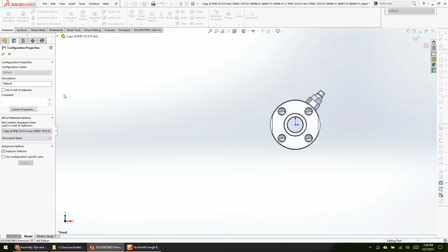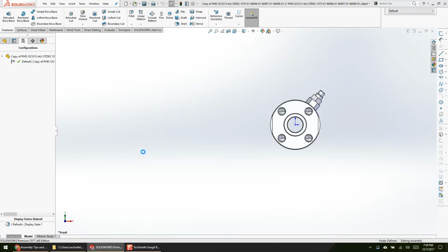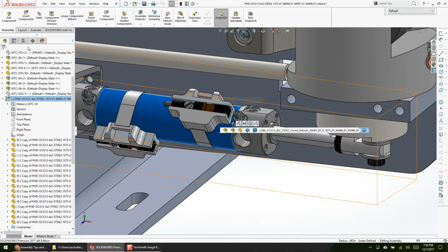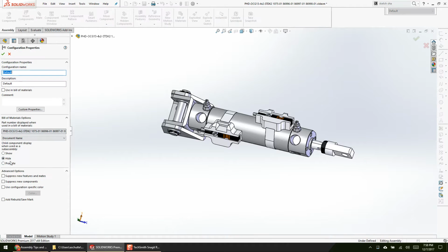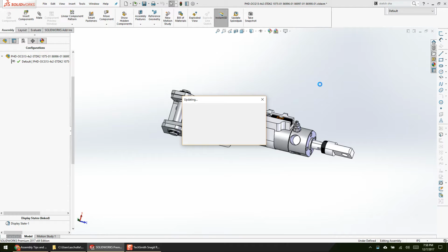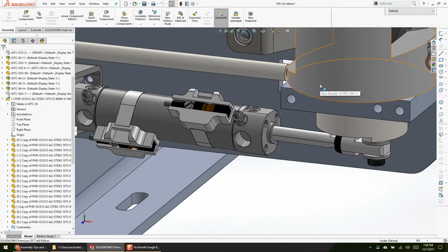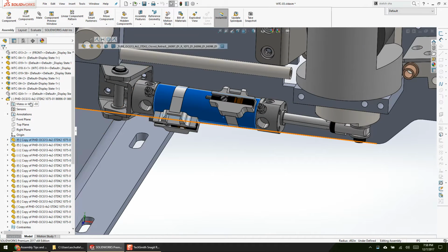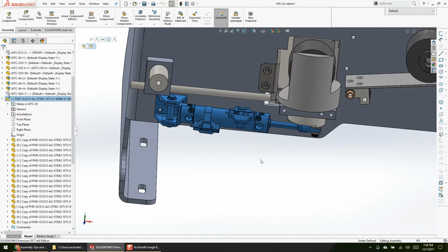In this particular instance, for that particular assembly, the bill of material properties are hide, so the children never show up. Remember, the assembly is a part, so the parts are just geometric references. So that's an assembly with no part files on the hard drive. They're all embedded in the assembly, much faster, less liability, less to break, less to go wrong. Very easy to do.